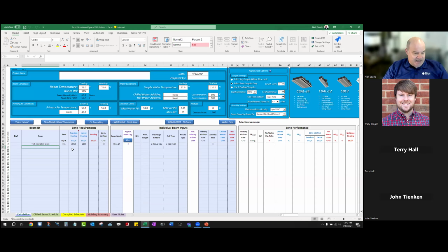You'll see actually that I've pre-populated the software with all these loads. In fact, I didn't mention this, but there's no heating required here because it's an interior space. So actually, we've only got these 3 columns here that you need to enter: sensible cooling, latent cooling, and ventilation. Putting in the square footage is useful because it helps calculate how many chill beams you need for this zone.